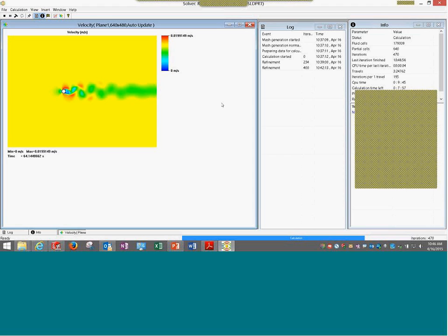But saying that, remember, capturing the boundary layer is important especially if the component is very small and we are studying a small amount of fluid area. But once the fluid area becomes big, the boundary layer may not be of too much significance. It is fine to neglect. However, if the user is interested in studying the boundary layer, then obviously we want to simulate it accurately, create an appropriate mesh, and then we can go. As well, in some tools we use something called prism elements around there, and they are supposed to be better for capturing the boundary layer, and that works.